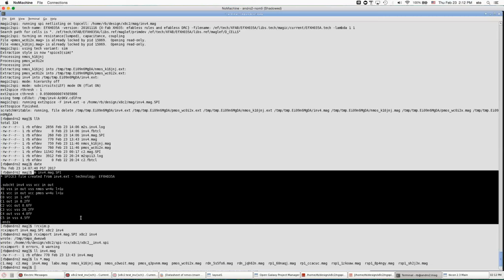All right. So a good LVS design with no LVS errors would essentially have, if not the same, similar SPICE decks from both these processes, right? Yeah. So now, if LVS is not clean, or you haven't run it, like I didn't even run it on this cell at all.